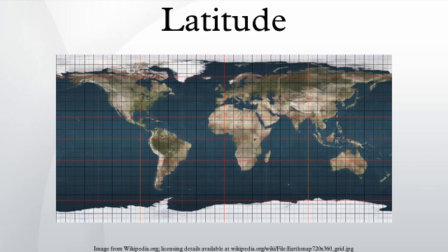Ellipsoidal coordinates. The reduced latitude can also be extended to a 3-dimensional coordinate system. For a point P not on the reference ellipsoid, construct an auxiliary ellipsoid which is confocal with the reference ellipsoid. The necessary condition is that the product E of semi-major axis and eccentricity is the same for both ellipsoids. Let u be the semi-minor axis of the auxiliary ellipsoid.